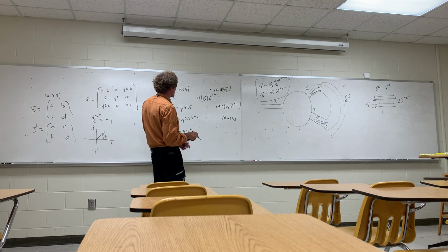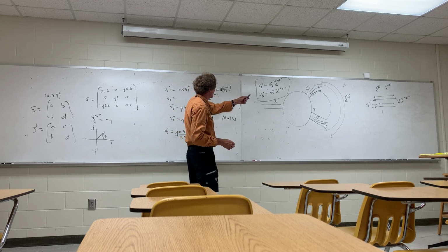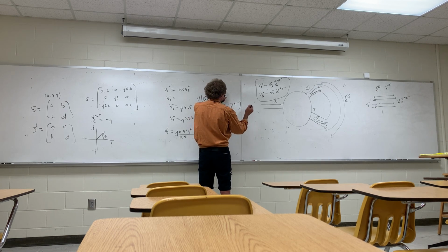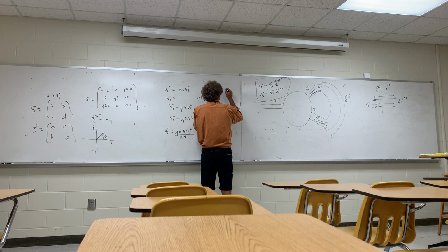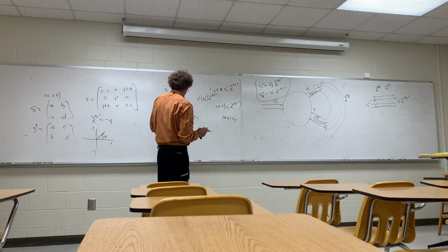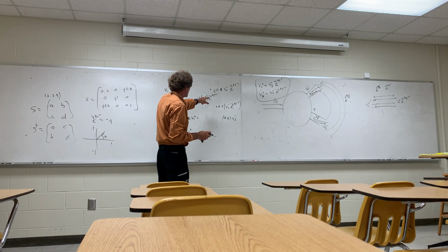All right, we can do it this way. This is going to be kind of an odd way. I'm going to start with this one. I see V3 minus, I'm going to go right here, kind of messy, but forgive me. I'm just replacing that V3 plus here with V2 minus, and it's times e to the minus j45 degrees. So now I've got it in terms of V2 minus. Then I look at V2 minus, and that's equal to j1 V3 minus e to the minus 45 degrees.